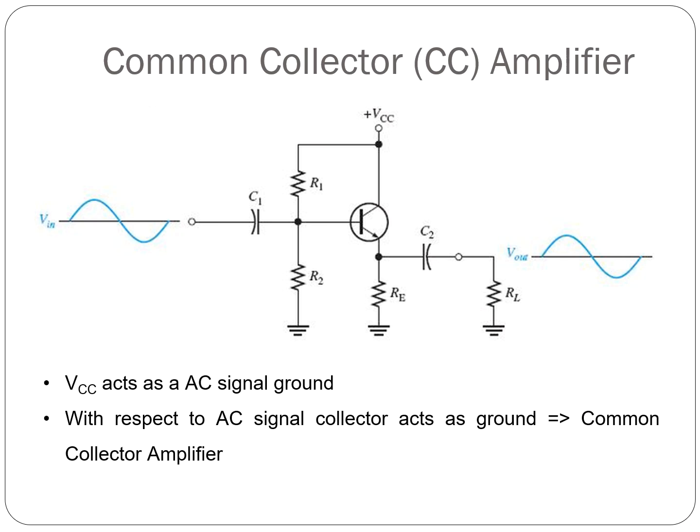And why do we do this? Because capacitors block DC, but they pass AC, and the power supply doesn't change with the signal. So that means that the collector is effectively grounded from the signal's point of view. So hence the name common collector.